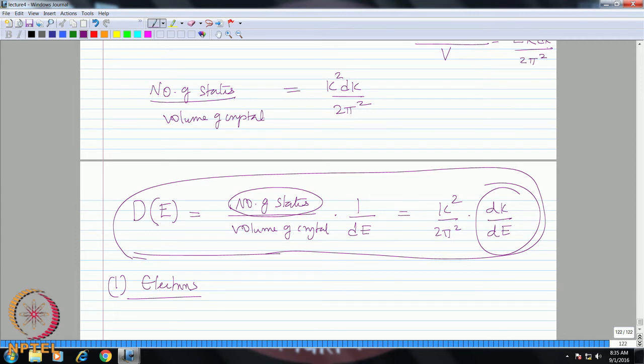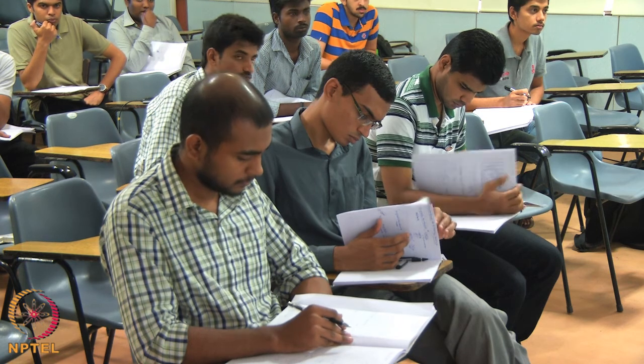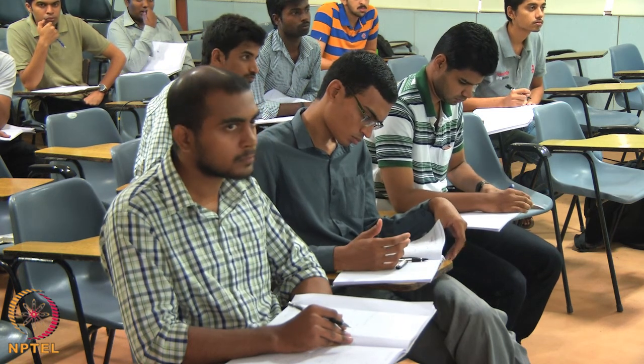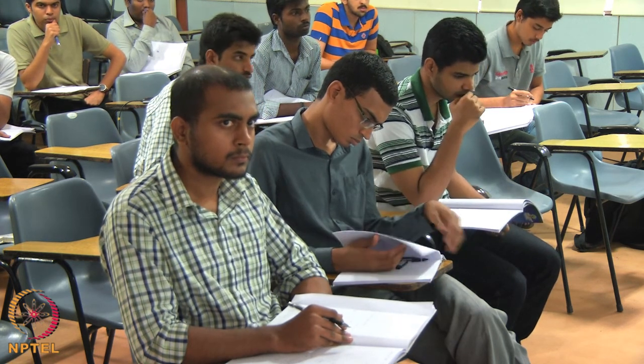But the dispersion relation is also having certain quantization, right? But then we are not really bothered so much about that, because for example, for the case of electrons, we have made a parabolic approximation. We know the relationship between E versus k as a continuous function. Similarly, with the phonon dispersion, we know the relationship between omega and k as a sinusoidal function.